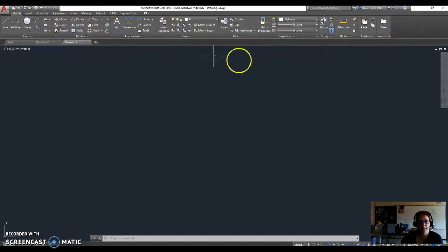It's really handy. The other thing that's really nice in AutoCAD is this command line. The command line tells you what's going on. So if you start a command, meaning you are telling the program to do something, it comes down here and it tells you line. If the command has a little triangle next to it, even like draw has a triangle next to it, it will draw, or it has more options below.